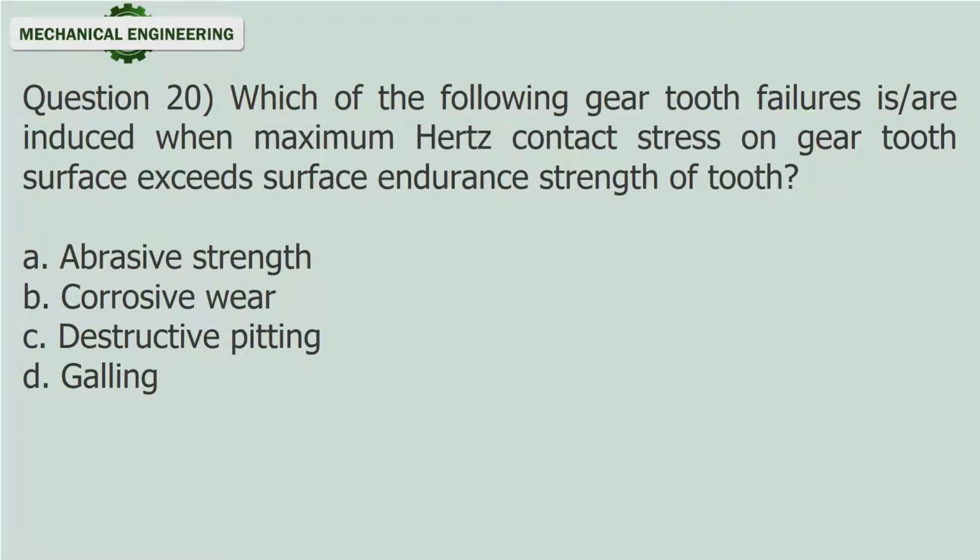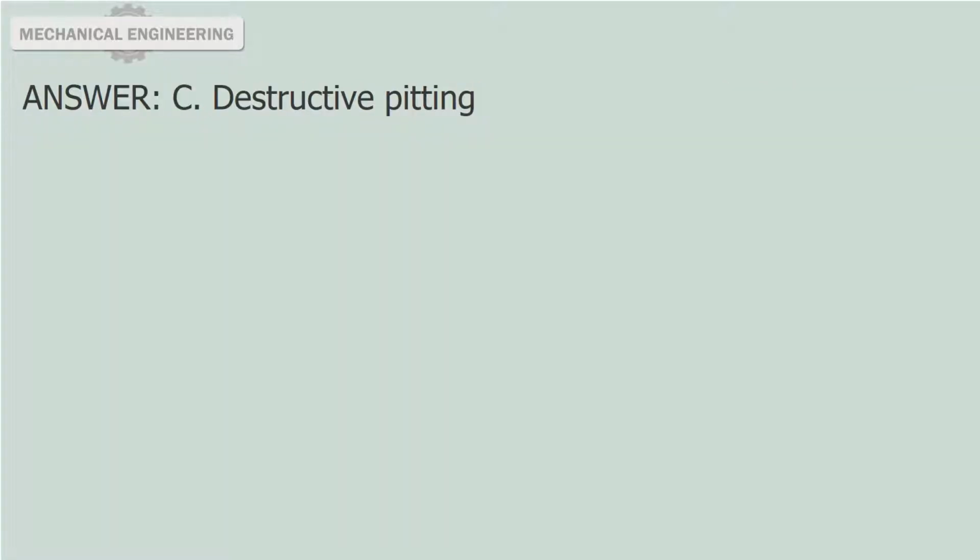Question 20. Which of the following gear tooth failures is induced when maximum Hertz contact stress on gear tooth surface exceeds surface endurance strength of tooth? A. Abrasive strength. B. Corrosive wear. C. Destructive pitting. D. Galling. Answer: C. Destructive pitting.